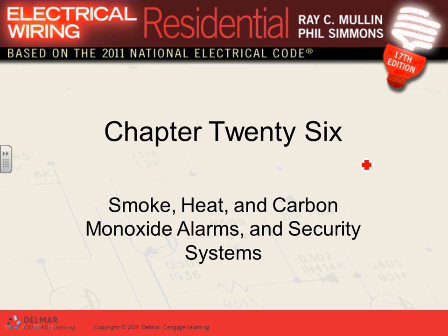We said we will have combination smoke detector devices installed in every bedroom and in every area adjacent to the bedroom, like hallways. They will be interconnected with each other as there will be a signaling line between them. They will be powered with batteries and powered from a lighting circuit in the area. That's what we said yesterday, right? And you guys installed a few of them in CAD.